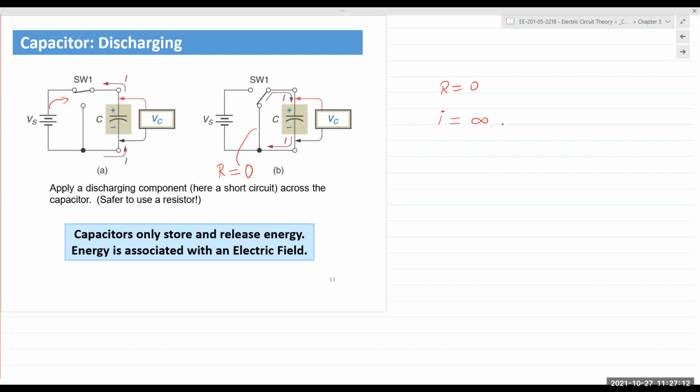So when they were shorted out, all of the energy of that cell or that battery is released all at once. Now with a capacitor, when you short out the terminals, the capacitor's storage is finite. You have a spark, charge is released, and it's done, it's empty. With a battery, it's an electrochemical cell, so there's still a lot of chemicals in there. So it will keep releasing the energy until it's empty. Well, by the time it's empty, it overheats, and boom. And that's what actually happened in real life.